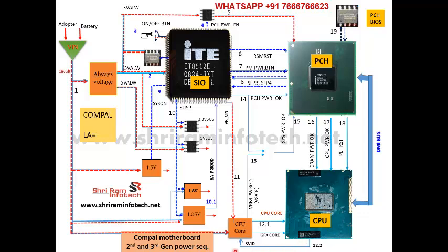This signal you can check with the help of an oscilloscope. That means your CPU is alive, the CPU is responding. Once the CPU communicates and the voltage is stabilized, after these signals one more signal is generated, called the VRM power good, or the V gate signal. It means the VRM section is working fine, VRM section is okay, there is no problem in the VRM section.